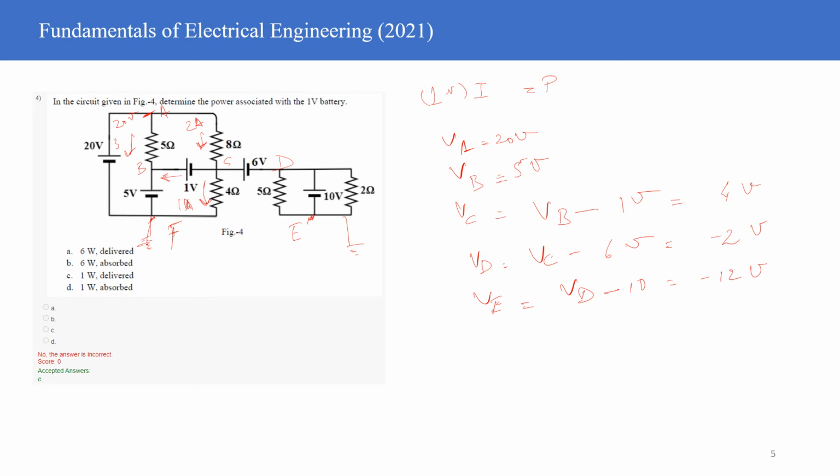So this particular node is grounded, and this particular node is also grounded. So is there a path for the current coming out of the 6 volt to find a path back to the negative polarity? Yes, there is. The current coming out can flow into the ground potential, and flow via the ground back into the circuit and complete the path. So in the hypothetical situation, the current can flow. But the question does not give you that. In the question this is a floating potential, so there is no grounding of this particular point. So no current is going to flow in this particular branch.